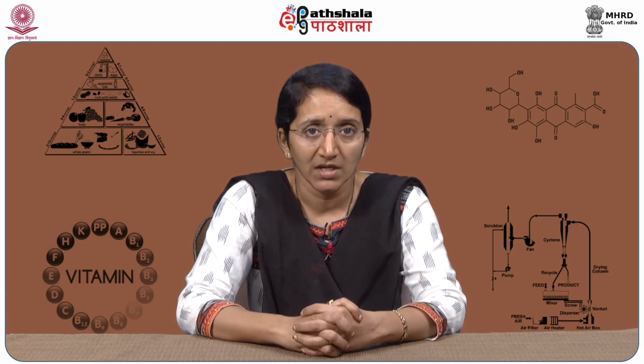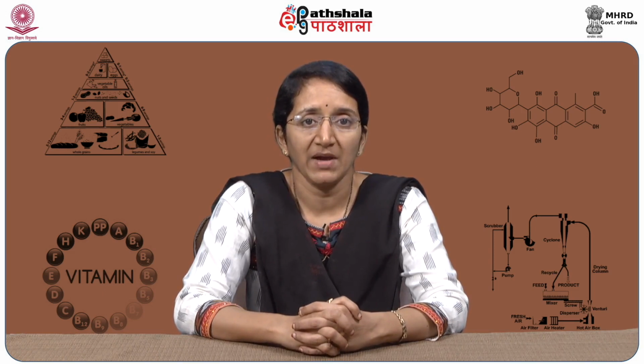Contrary to popular opinion, ultra-high temperature processed milk and juices do not contain any added agents to provide the longer shelf life or storage at ambient temperature in the laminated cartons. The products are preserved exclusively through application of heat. It is critical that the sterilized products are transferred into the packaging equipment under aseptic conditions only, to avoid contamination after thermal processing. If a product is mentioned as UHT treated, it has to be taken into account that UHT treated products are not necessarily aseptically packaged.